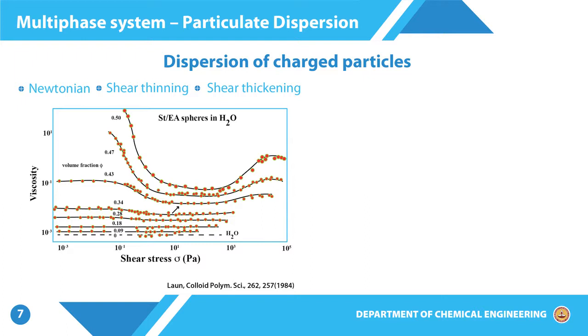So, what we can clearly see is the clustering at lower stresses and at higher stresses is not very different, because the particle concentration is not high enough for the clusters and percolated clusters to form. Therefore, what we see is very little change in viscosity, but clearly the time scales associated with the overall stresses here are associated with the breakage of clusters or alignments of clusters, depending on the type of particles and type of mechanisms we might have in the material.